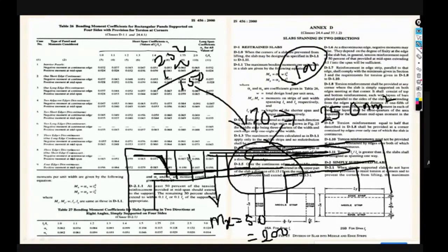The second thing is we are providing stirrups in the beam. That bent up bar is provided only to reduce the shear reinforcement or to reduce the shear stresses at the corner. If you are providing the shear reinforcement, there is no need to provide the bent up bar in the beam. As per my experience, that is the main reason to convert the bent up bar to straight bar. And yes, if you provide some curtailment in the main bar, obviously it is economical.